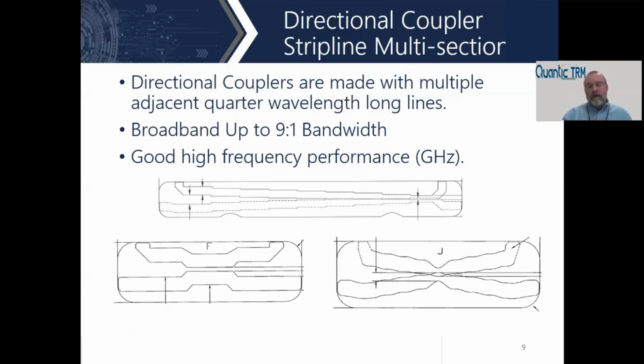And that's why the design in the lower right very often is more applicable to very high frequencies, whereas the one up on the top with the steps on it very often is used for mid-range frequencies. And that's just a matter of trying to optimize directivity for these sorts of structures. There's a lot of detail that gets involved in designing these. They are by no means simple to design, but we're quite successful doing it here at TRM. And this is just one example of how we expand the bandwidth of an individual coupler.